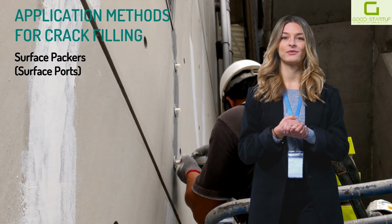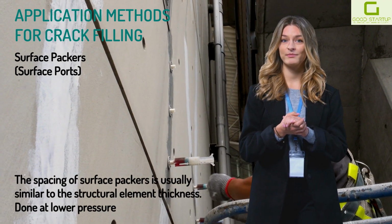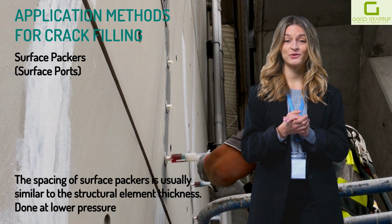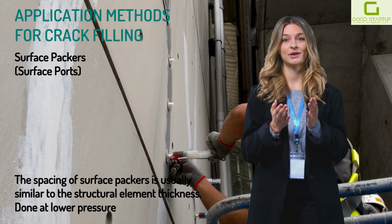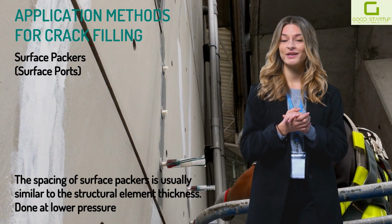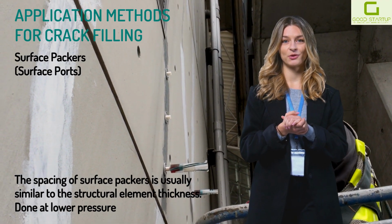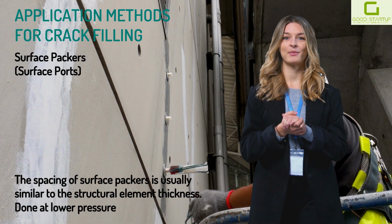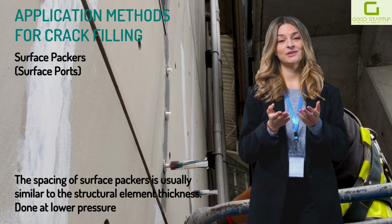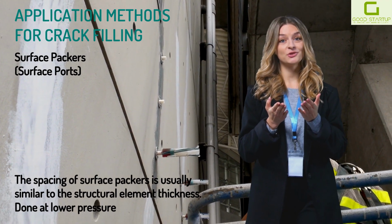Surface packers, surface ports, when drilling is undesirable or impossible. For example, in pre-stressed concrete elements, thin concrete sections, or architecturally sensitive surfaces, surface packers are used. Surface packers are small port nipples that are glued directly over the crack on the surface using a strong epoxy paste. The rest of the visible crack is also sealed with the same epoxy paste except the port openings. Once the epoxy paste has hardened, the crack becomes a closed conduit and resin is injected through the surface packers.